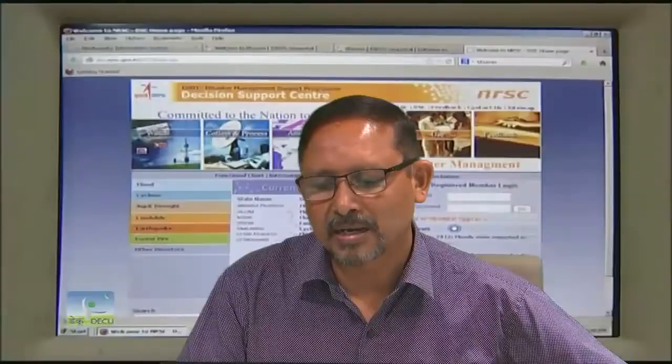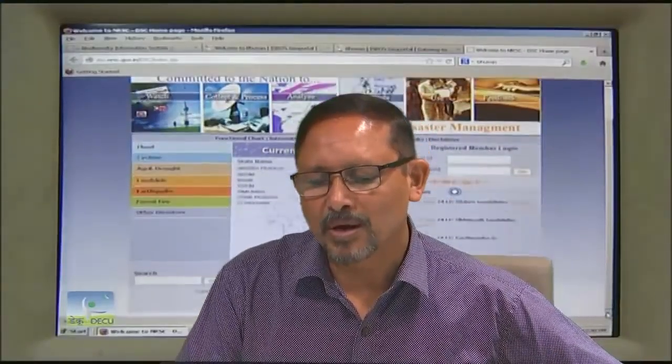How can we predict a rainwater harvesting system? I told you the DEM is used to find out the terrain wetness index, which is one index. It shows where water is getting accumulated. So the point where you are getting a high terrain wetness index value, it means water will move there. So there you can construct a pond or any tank for collecting the rainwater.